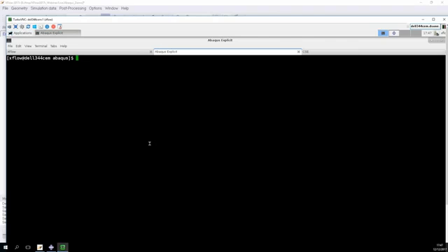Now we do exactly the same for Abaqus. So we run our Abaqus simulation, and as you can see, we're specifying again the host name and port of the Cosimulation engine. And that's the XFlow coupling.imp file that we created, the input file.